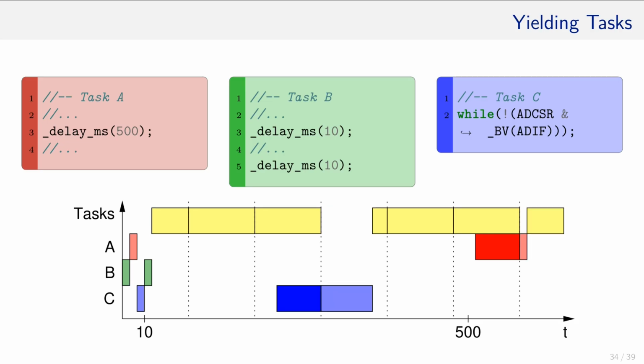So what if we again divide our time window that we currently observe into multiple frames? But now the MCU wakes up at the beginning of every time frame and checks if any condition of the tasks to continue has been fulfilled. If there's none, it sends the MCU back to sleep. If there are, it executes the tasks and goes back to sleep when there is none left anymore.